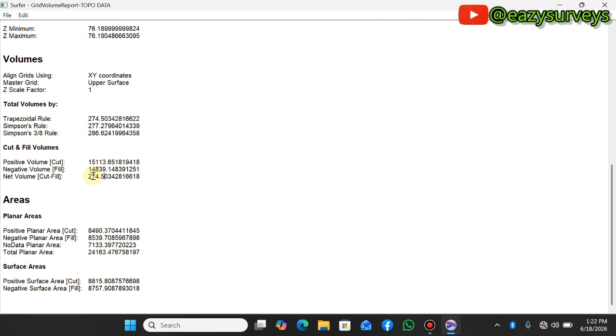That is to say, there is no need for my client to go and buy extra materials for the project site. Do we get that? That is the advantage of this report. After you conduct your own report, you may find that your level of cut is lower than the fill. That simply means you are going to have a negative value. If you have a negative value here, it means your client will need to purchase this quantity of material to achieve the uniform designed proposed level for the project site. That is the beauty of cut and fill volume analysis.